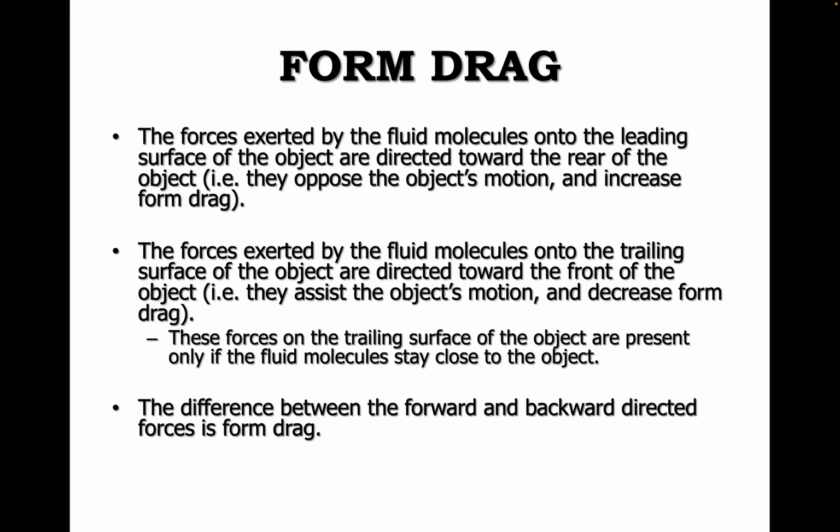So with form drag, there are some air molecules bouncing off the front, and there are some bouncing off the rear. The ones bouncing off the front are resisting movement. The ones bouncing off the rear are assisting or helping with movement. And the difference between the forward and backward directed forces is going to be that form drag.